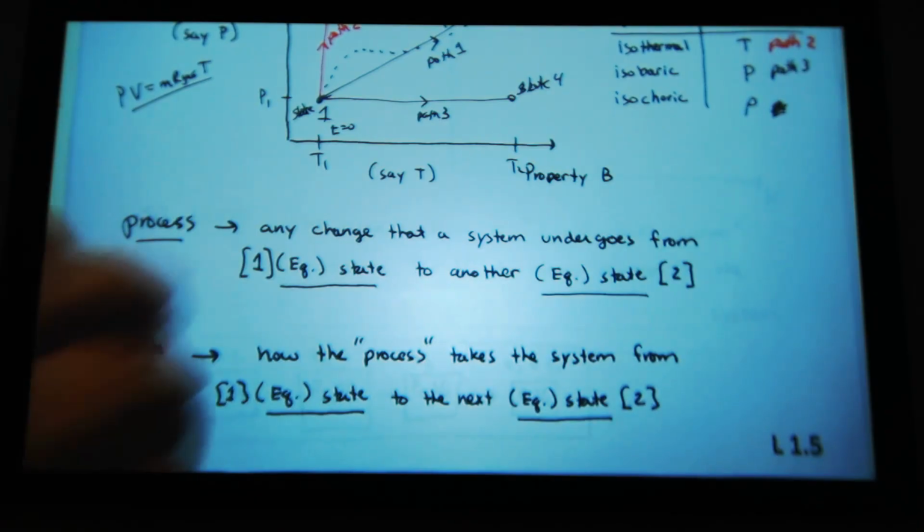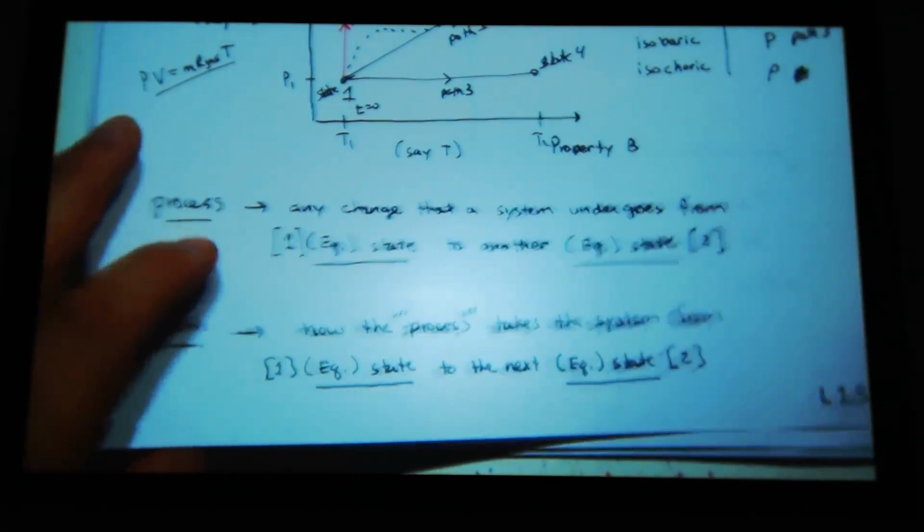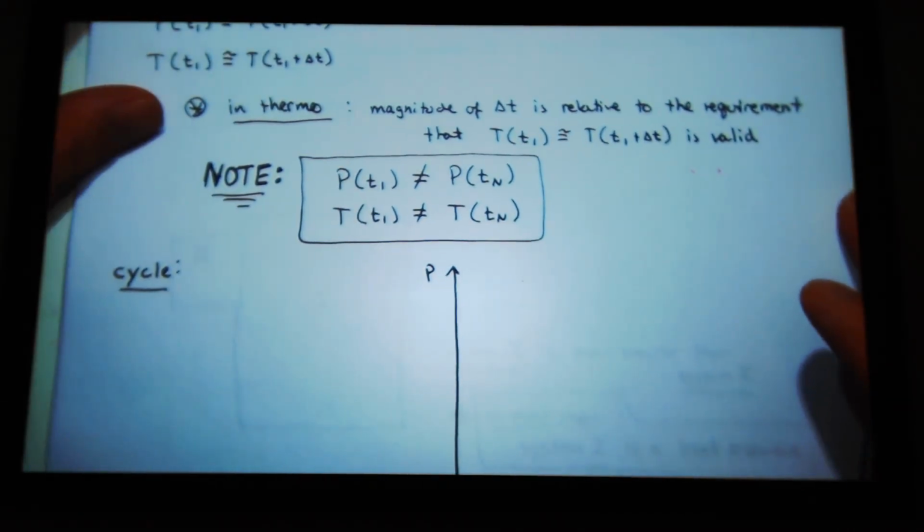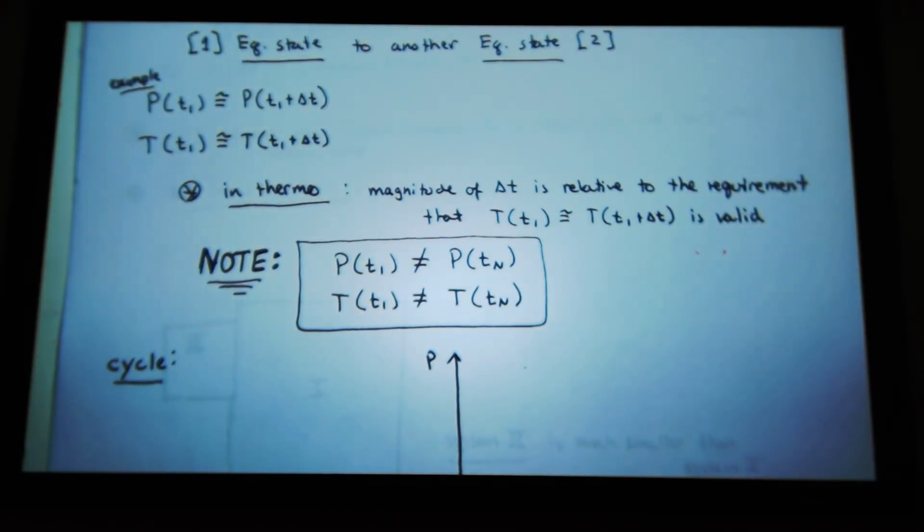Yes? So to apply this, we would take, using the example of a piston engine, you would have the state at ignition followed by the state when the piston reaches bottom dead center. Sure, yes, and combustion is complete, so that would be your first and second equilibrium, and then we would have another process for the exhaust stroke when the piston. Yeah, you'd break it all down. If you have a 4-stroke engine, you have 4 processes. A 2-stroke engine, you would have 2 processes.